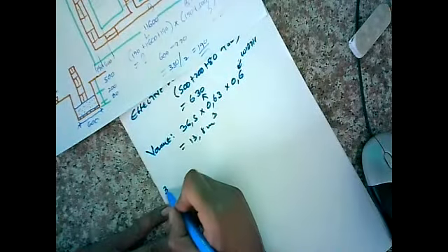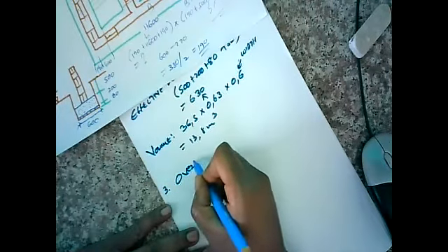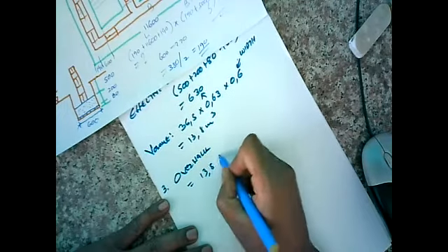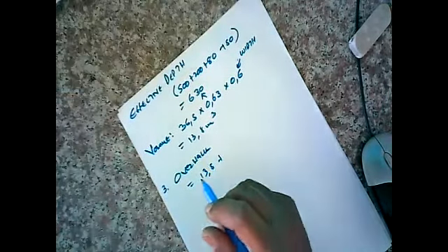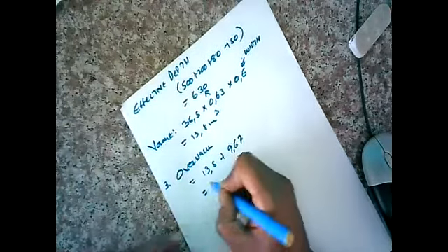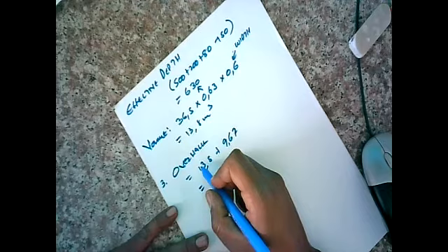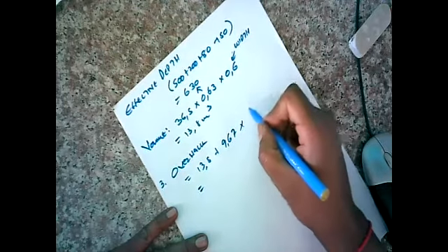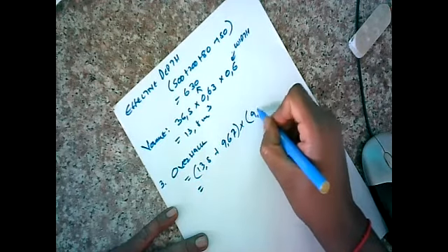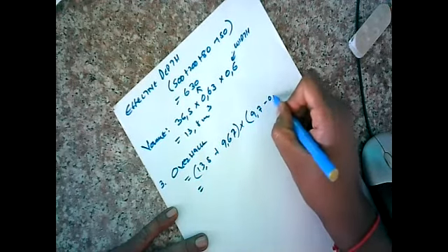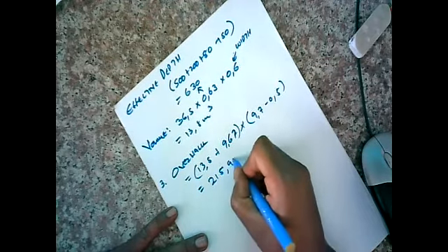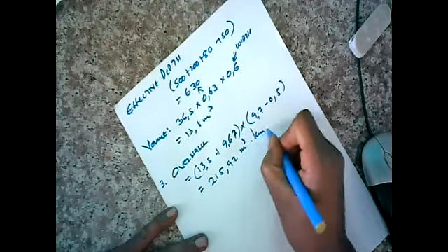Now we can move on and we say 3, overhaul. 13.8 plus, what was our top side? 9.67, giving a value of whatever. That times 9.7 kilometers minus 0.5 is free haul, and we get a value of 215.92 meter cube per kilometer.